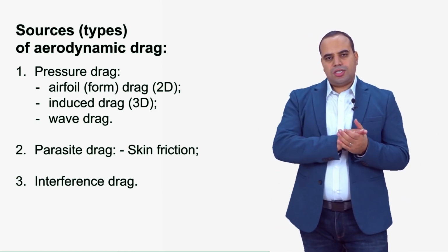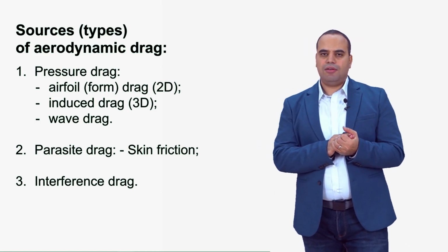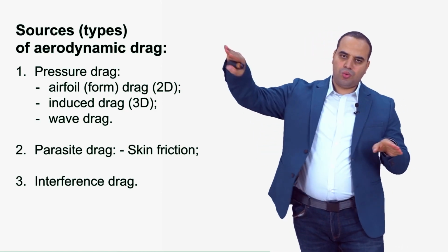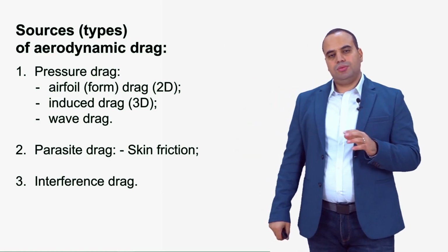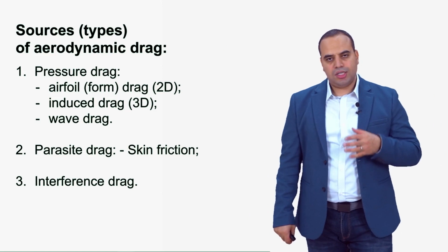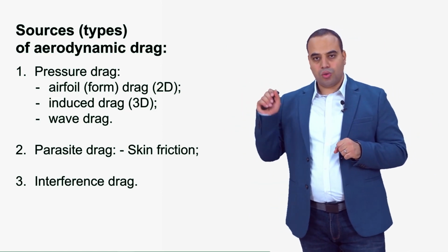And so for now, I can say just that because when we fly at close to the speed of sound, we have a barrier, which is called the shock wave. And that shock wave is also something that prevents the aircraft motion forward in a tremendous way, right? So the drag increases like 4 times, just because of this shock wave. So it is called the wave drag.